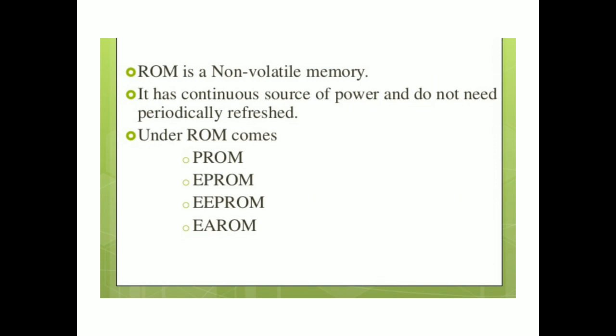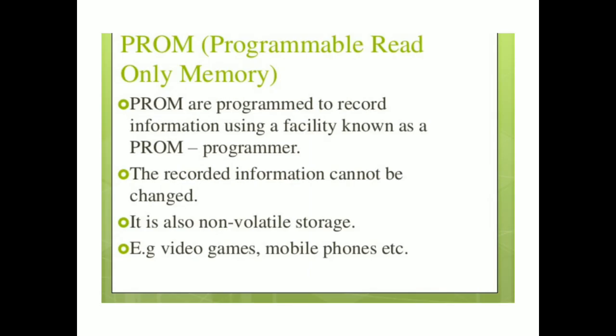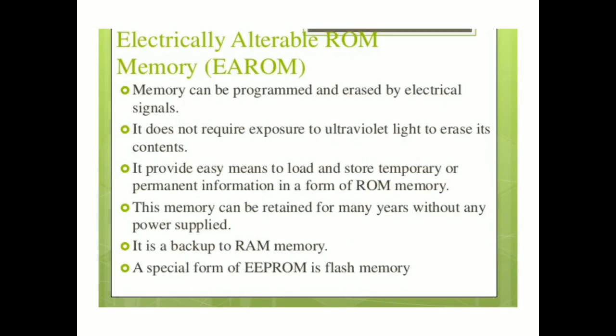Another disadvantage of this technique of erasure is that the EPROM chip has to be taken out of the system board and placed in an EPROM eraser's chamber. EPROMs are cheap and reliable, hence they are widely used. EPROMs are used to store programs, data or any kind of information which is permanent but needs updating.